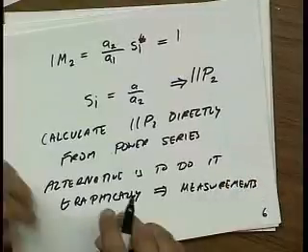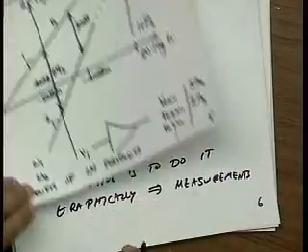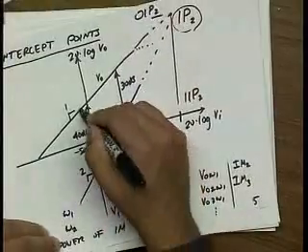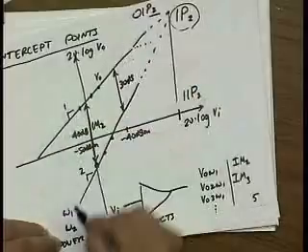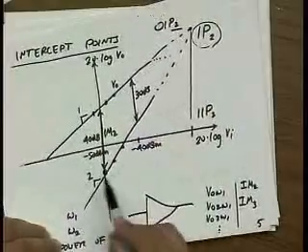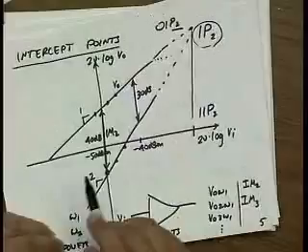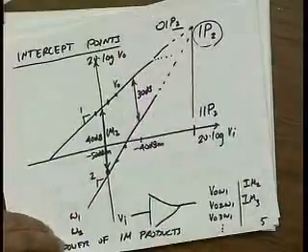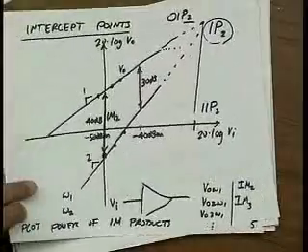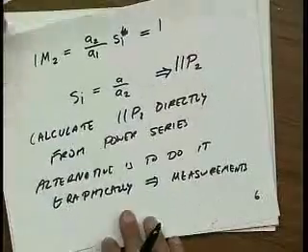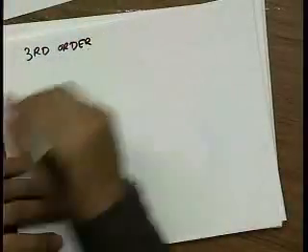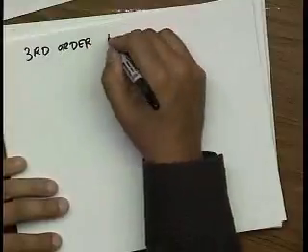We typically will measure the IM at several input points, basically verify that the amplifier actually fits within these lines. We do that just to make sure we're not crazy. Maybe the amplifier is hooked up incorrectly. Make sure the slope is right, and then you extrapolate to get your IP2 point. Okay? Well, a very similar concept is your third order IP point. And in fact, it's a more important concept for most systems.